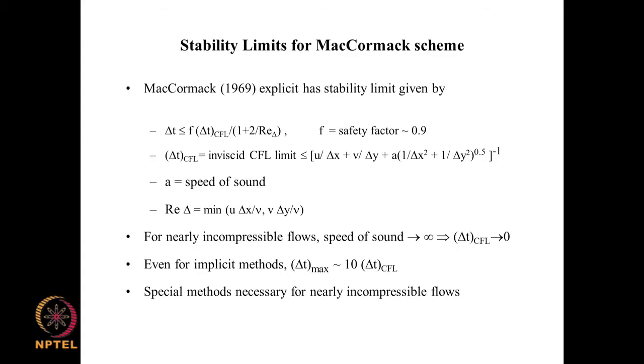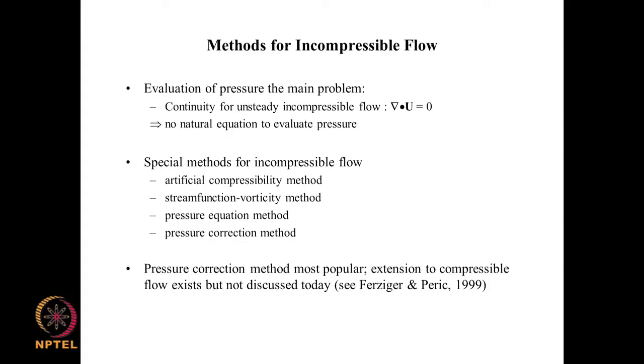So, if density is not there, then the linkage between the continuity equation and the momentum equations through pressure, density and the equation of state is gone, and in such a case we will not be able to use the density based methods that we have seen in compressible flows. We also saw that there are special methods that have been developed: the artificial compressibility method, stream function vorticity method and pressure equation method. These are the ones that we are going to learn in this part of the module.